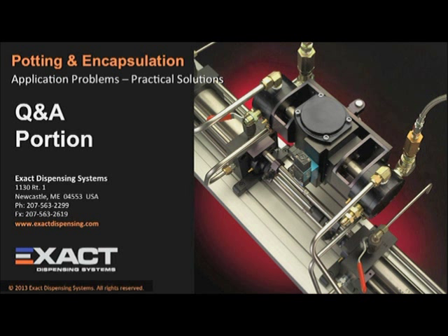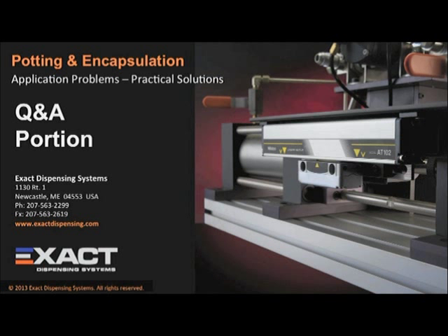Unfortunately, we find some folks that don't bother to put nitrogen on the polyol side, and you need to add nitrogen on both materials. If you don't, when the wet polyol contacts the isocyanate, it still starts the same CO2 producing reaction, and it makes bubbles in your part. So not only is the moisture a problem on the isocyanate side, but it's also a problem if you bring in moisture from the polyol. The polyol is usually pretty benign. You wouldn't know that there was a problem there until you combined it with the isocyanate.